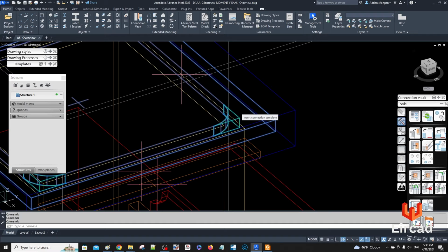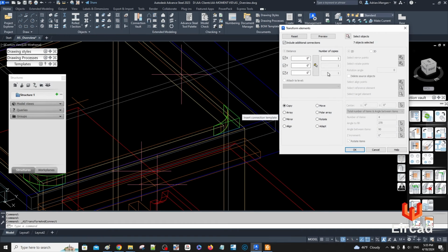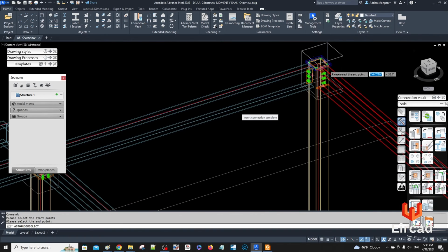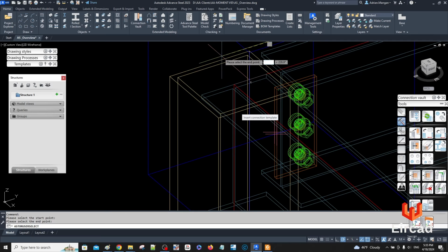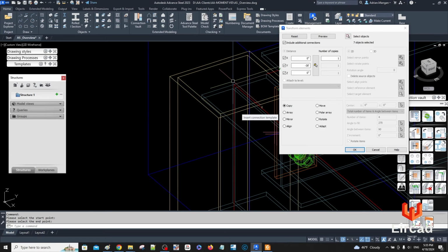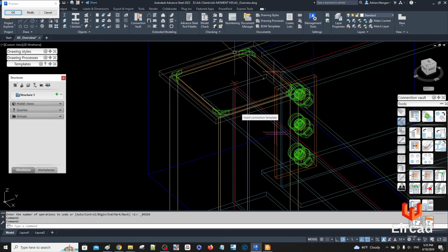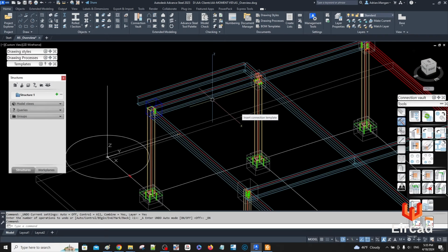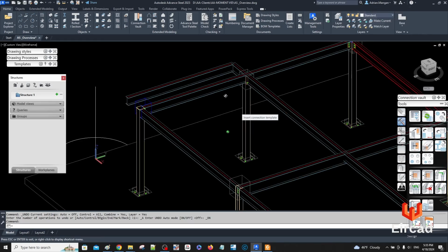And if I copy these, advanced copy, from the node to the node, and then preview, you can see it'll do the same thing, and it brought the weld over as well. Okay, so you can do it that way also. So there's only two, so there's no point. You're better off just copying it like I just did, not the other way.